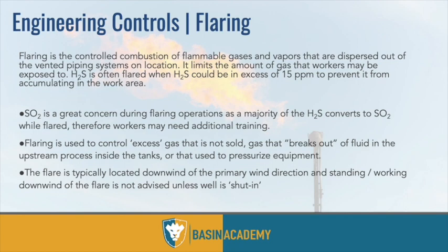So just keep that in mind. At that point, SO2 is the greatest concern. So those flare stacks being higher is better, right? Because both SO2 and H2S, when they come in contact with wind, have a high dispersion rate. So when wind hits it, boom, it goes from high percentages to very low parts per million quickly.